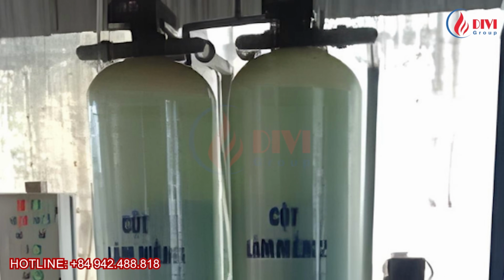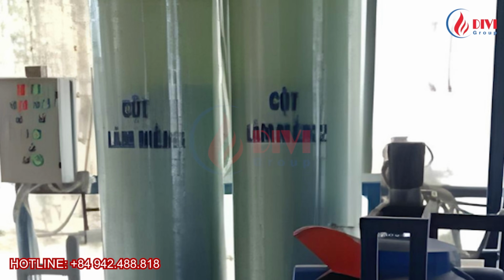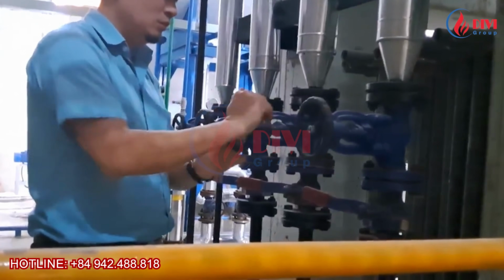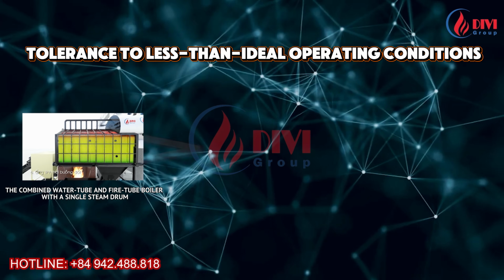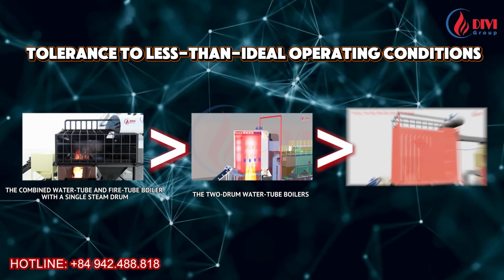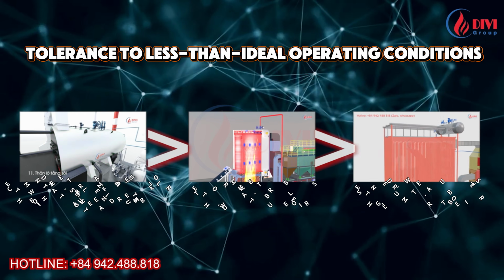For all these boiler designs, poor water treatment chemical control, irregular blowdown, or failure to check for scale buildup regularly can create a high risk of boiler damage. In terms of tolerance to less than ideal operating conditions, fire tube boilers generally provide the greatest margin for error. Two-drum water tube boilers are less forgiving, while single-drum water tube boilers are typically the most sensitive.